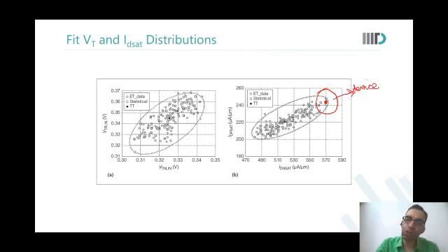Until now, we were looking at lot variations. To validate a design with device variations, you go to the SS corner or FF corner or whatever corner you're talking about, and you run Monte Carlo there.